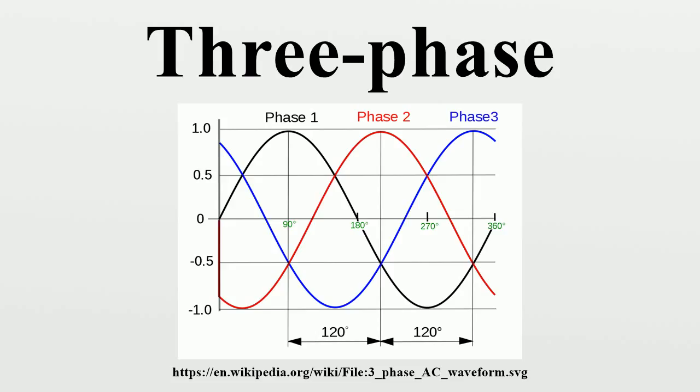However, it has a greater redundancy as it may continue to operate normally with one of the three supply windings offline, albeit at 57.7% of total capacity. Harmonic currents in the neutral may become very large if nonlinear loads are connected.